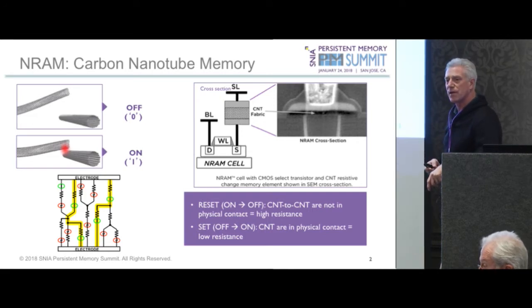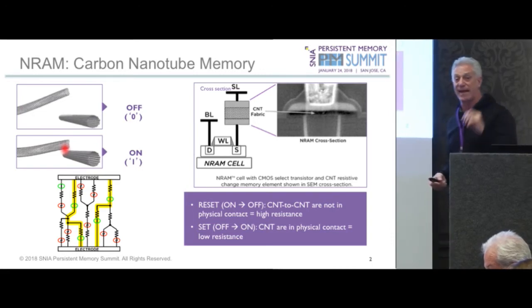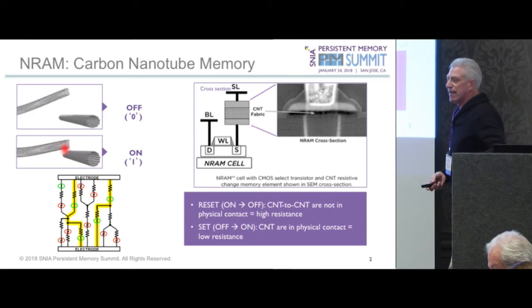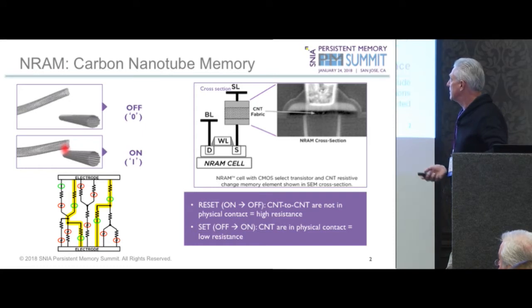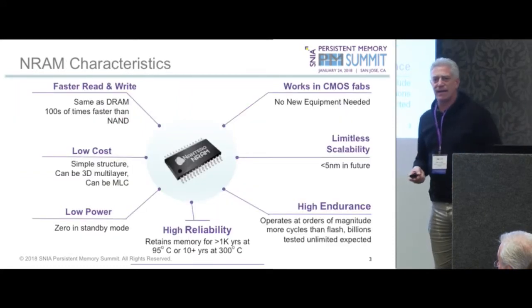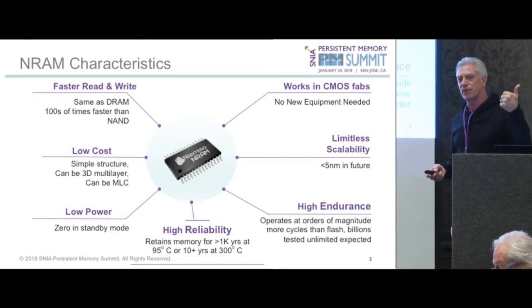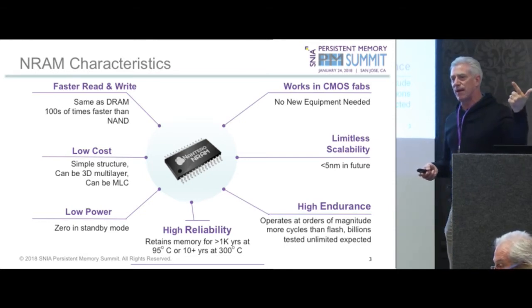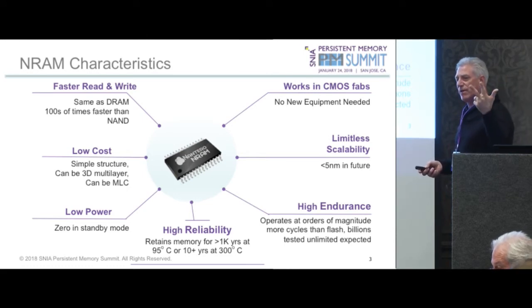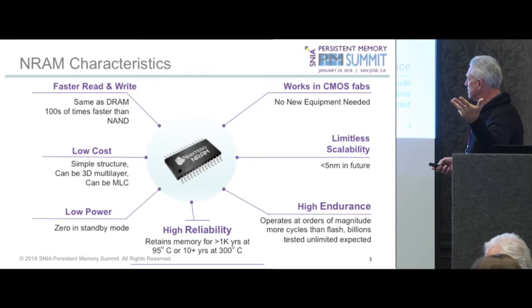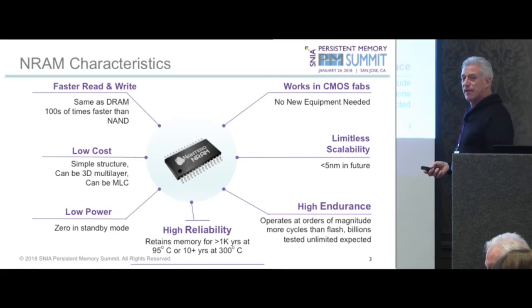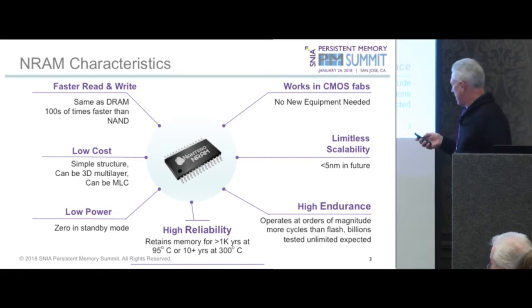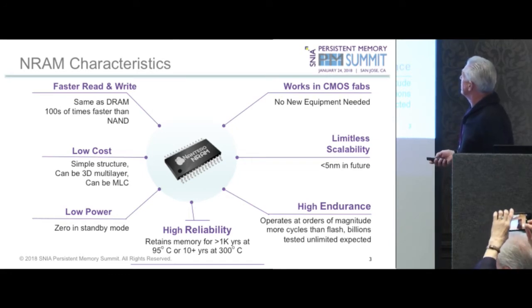It's essentially a resistive network that is switched into ones and zeros using the atomic interactions of carbon nanotubes within the substrate. It has no dielectrics. It's basically a standalone resistive memory type. What is it? It's essentially DRAM performance. It is DRAM endurance. It has no heat sensitivity. It scales. And I want to avoid using any magic references, but it's a pretty cool little memory. I think you'll be quite happy with it when you see this in your systems.